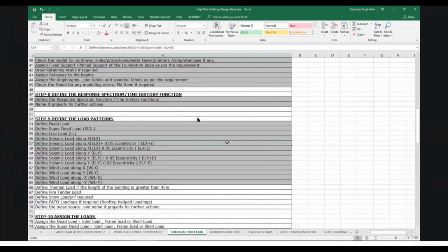Calculating wind loads itself is somewhat a tedious process that has to be done by experienced structural engineers, especially for high-rise buildings. You cannot ignore the magnitude of wind on the top of a 100-meter building or the top of a 200-meter building. Building sways a lot, so we need to calculate wind load with great precision and with great correctness, otherwise it may lead to an error.